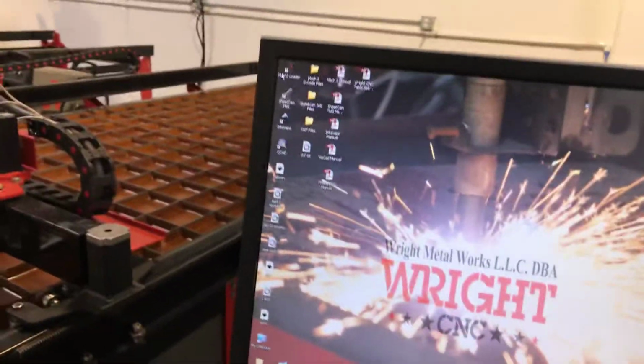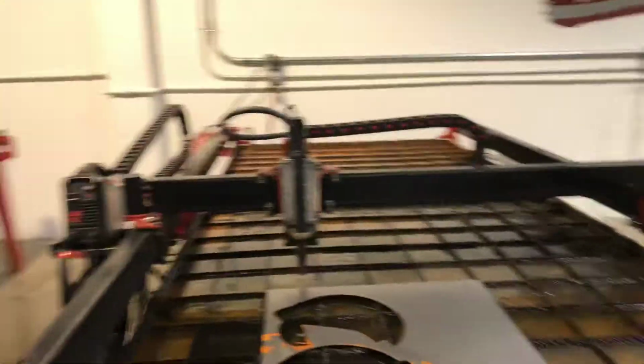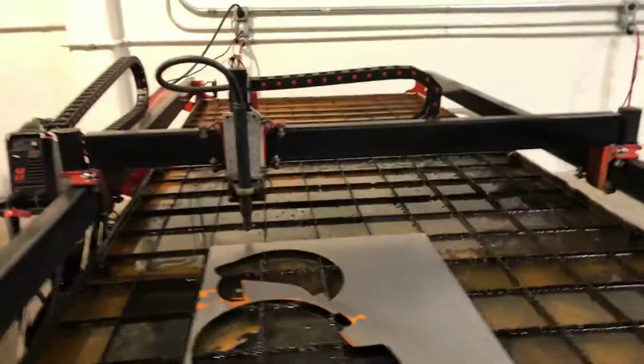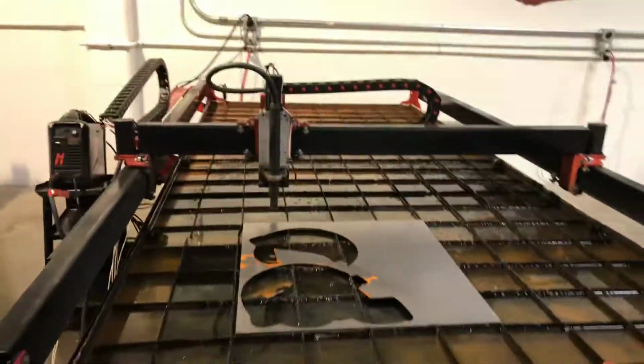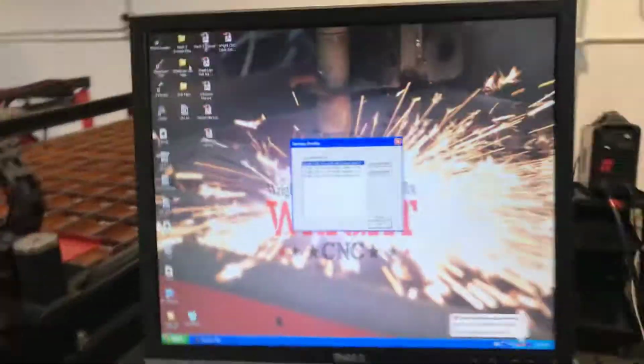All right, so let's talk about the table and getting all of that set up. To answer your first question, the reason it was trying to move the way it was is strictly because you were starting from the middle of a specific line of code, and it wasn't at that position, so it does a weird path travel to get to that position. We want to avoid that, so let me show you exactly how we do this.